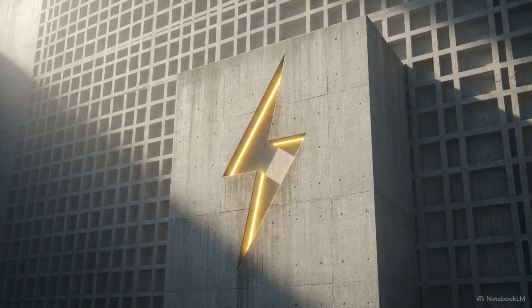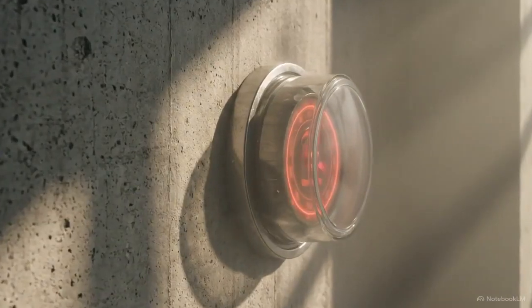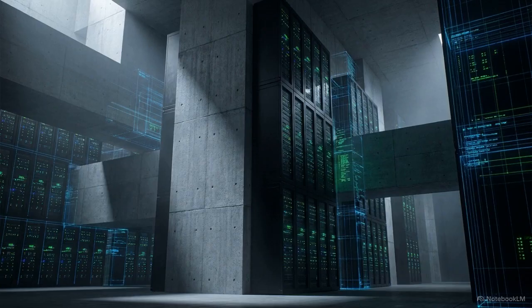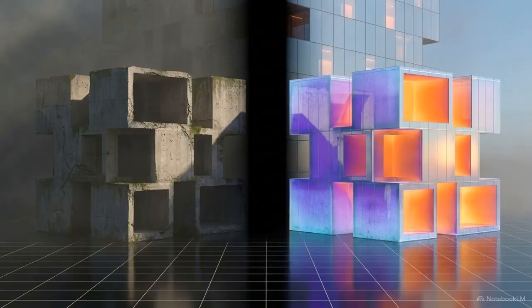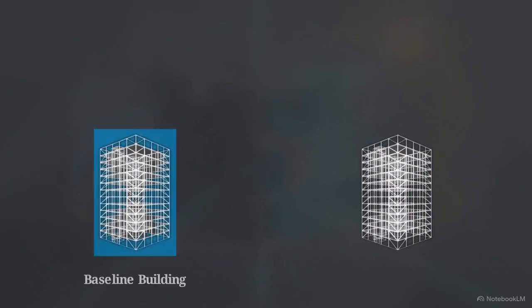We begin with the most heavily regulated domain, energy modeling. This simulation predicts the annual electrical consumption required to power the building's HVAC systems, its overhead lighting, and internal equipment. Proving its efficiency requires a strict comparative analysis. Regulators do not look at a design's energy use in isolation. They mandate testing the proposed building against a specific control model. That control model is the baseline building. It precisely matches your proposed building's geometry, built to bare minimum code requirements.